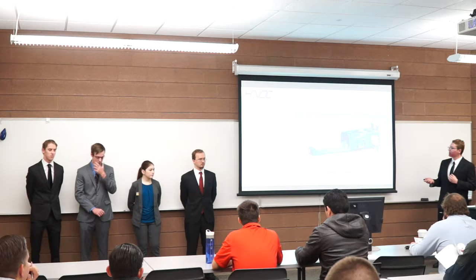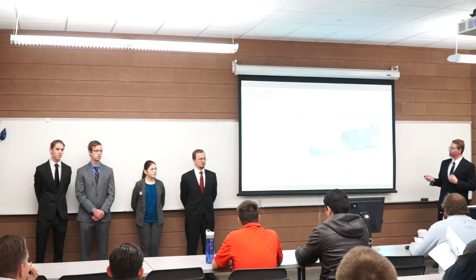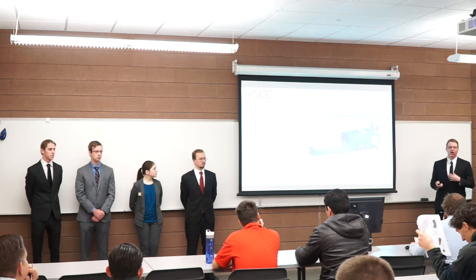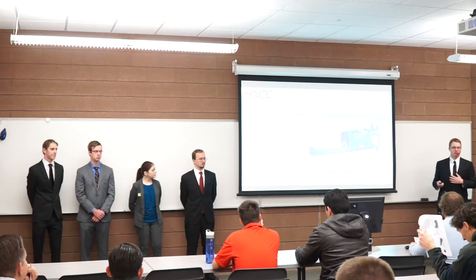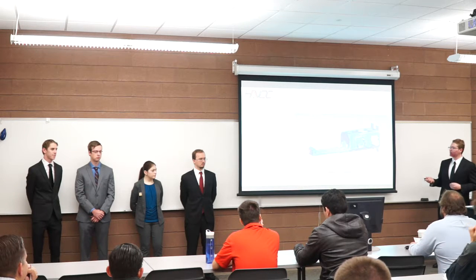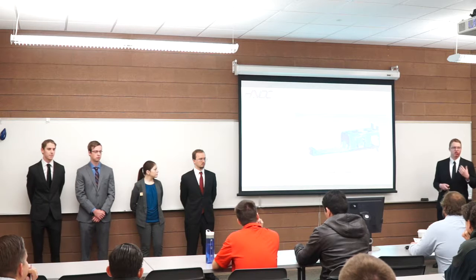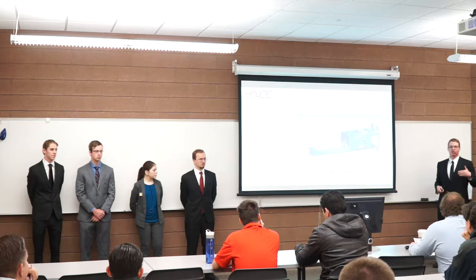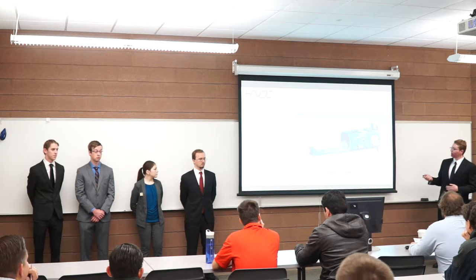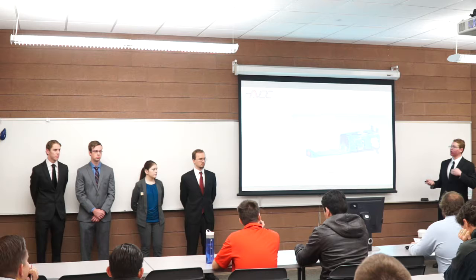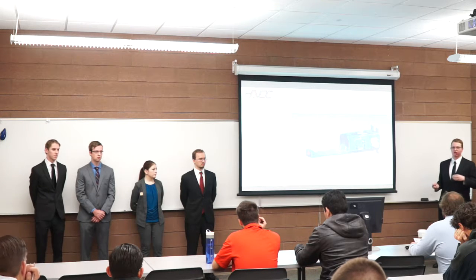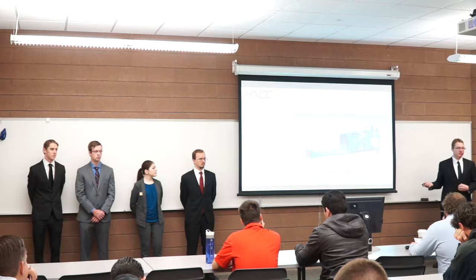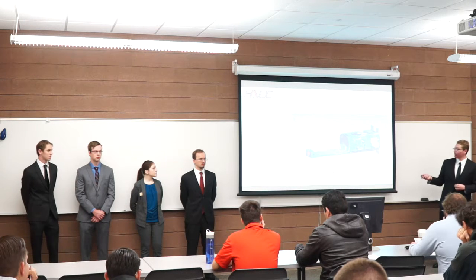The ANSYS simulation shows that the maximum forces will be felt here, and maximum stress and strain will be felt here. But according to our data sheets that we reference, they do not exceed the maximum ultimate tensile strength and strain. The ultimate tensile strength is 55 megapascals, and this is 44 megapascals. And on the strain, the maximum elongation of the material was 24%, and it does not exceed 4.04.